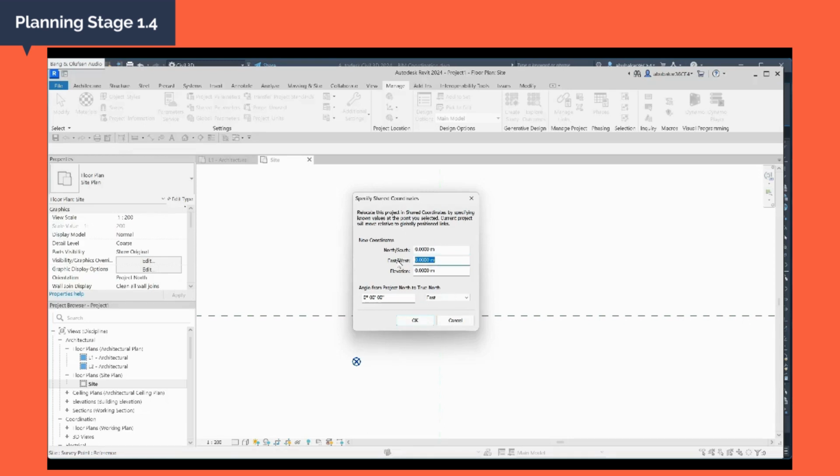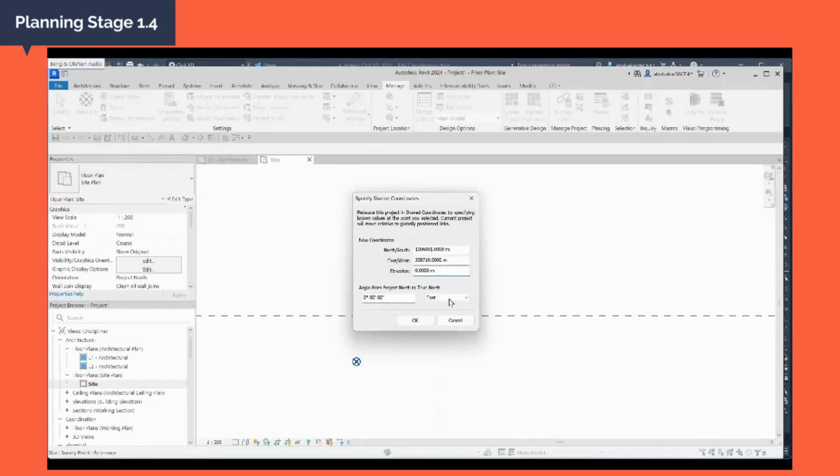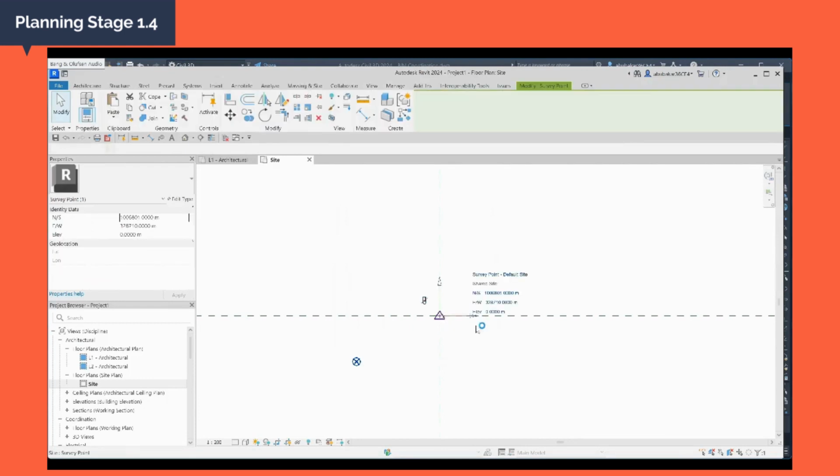So our east-west, which is the X, is given, which I've copied. Then our Y, which is the north, is given as 106086801. So this is it. If you confirm, let's go back to 3D. You see, this is the Y, which I've coordinated here. So you press OK. When you press OK, you have set your base reference. You can see the point that's defined.